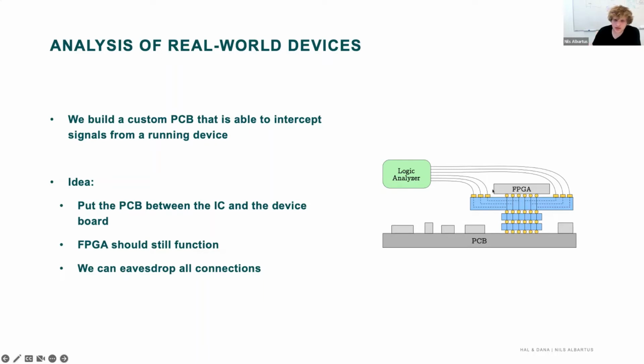And this allowed us to observe the inputs that are going into the FPGA during runtime. So we actually had the correct inputs, like the real world inputs of the design that are applied there. And we recorded all of them with the help of a logic analyzer. And in the end, we applied them in simulation.